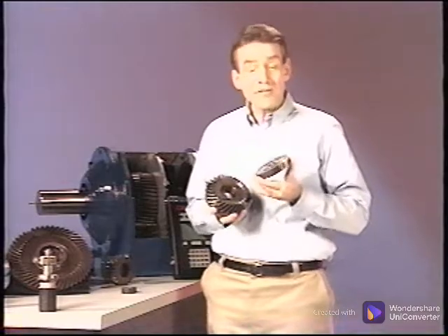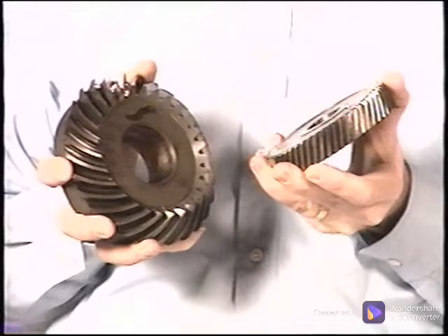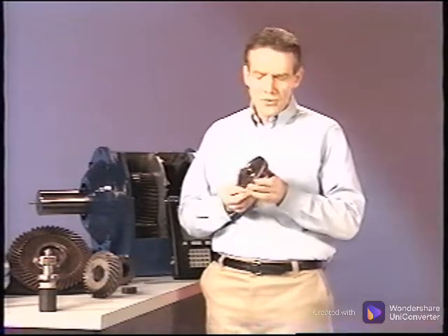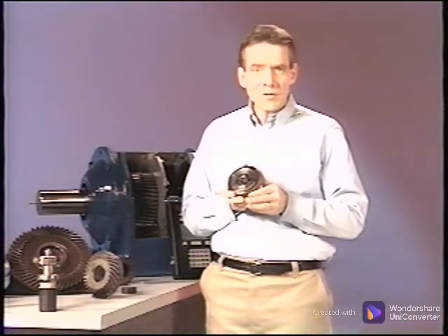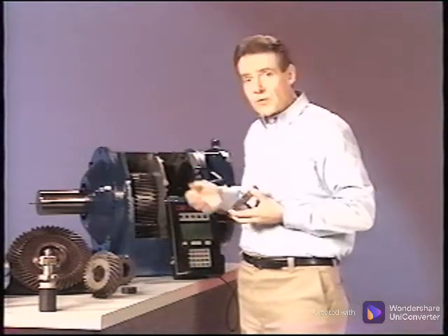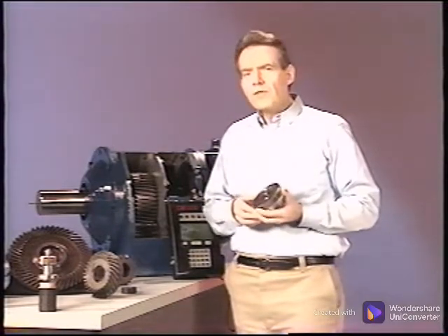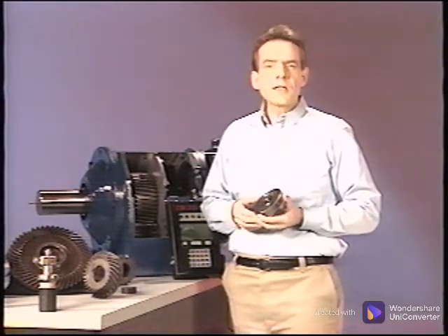Although these two gears look very different, they still perform the same job: transmit torque and change the speed without slip. The ability to run at high speeds, the relatively low cost of the torque transmitted, and the high power to size ratio make gears the drive of choice in most industrial applications. The power can be transmitted in line, such as this gearbox, or at an angle. In either case, the speed of the driven unit can be increased or decreased, and thereby affect the transmitted torque.